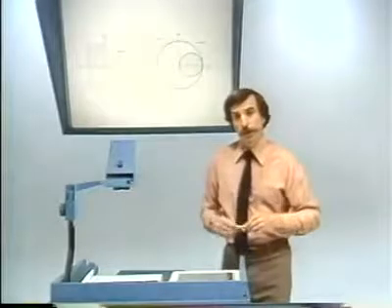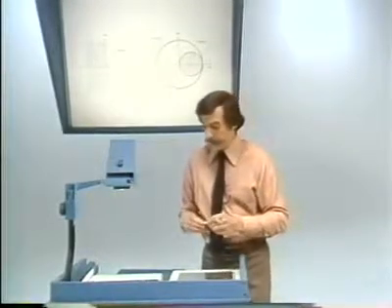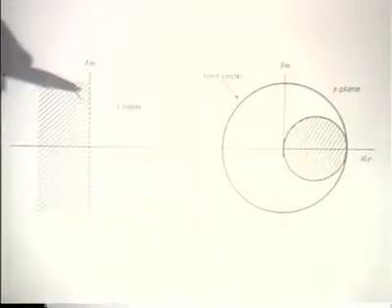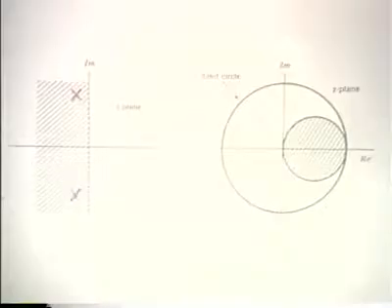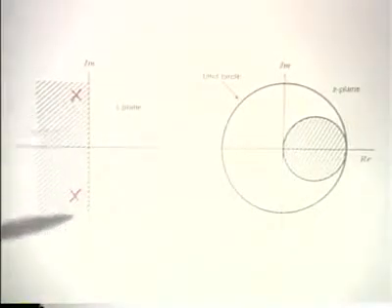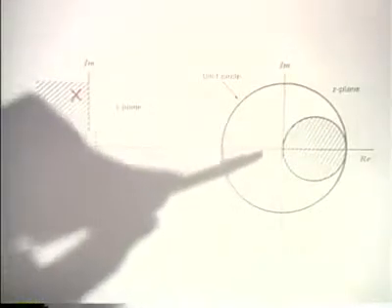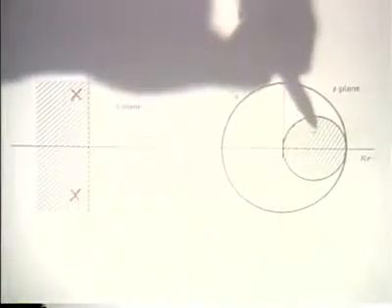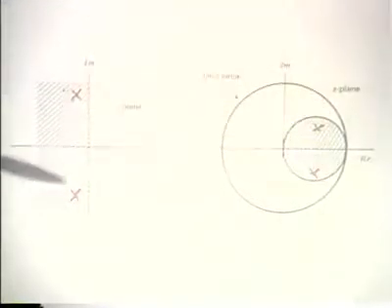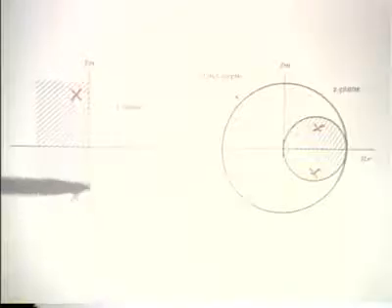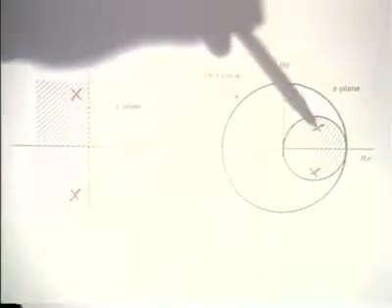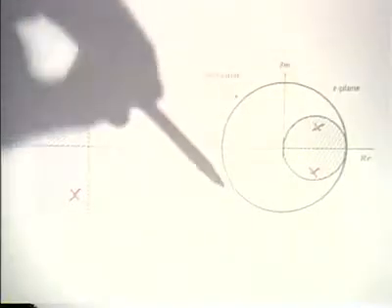To emphasize this point even more, suppose, for example, that we had a pair of poles in our continuous time system function that looked like this. Then where they're likely to end up in the Z-plane is inside the unit circle, of course, but if the poles here are close to the j-omega axis, that means that these poles will be close to this circle, but in fact might be very far away from the unit circle.